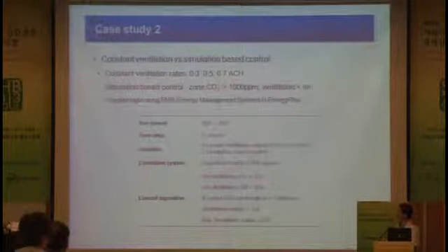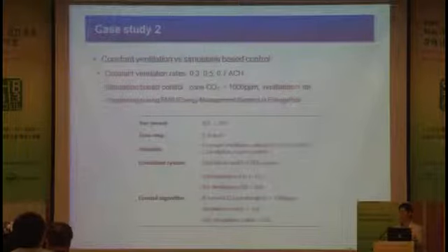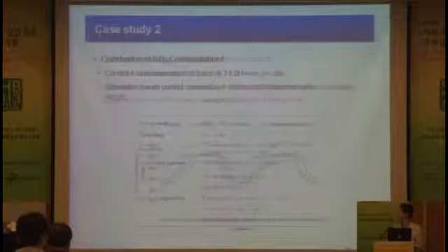We compare this current control approach with the simulation-based control, which means if we have 1000 ppm of CO2 in a room, we run the ventilation system. And we realized this simulation system with EMS in EnergyPlus.